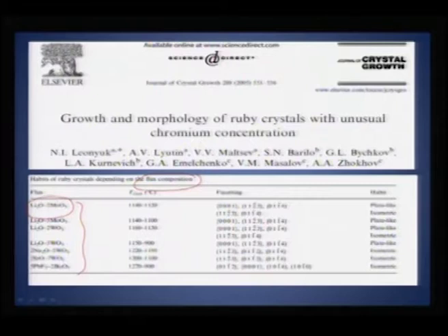If you take and put it in a furnace in a crucible, you can actually melt it between 1120 to 1140 degree C. Then this lithium oxide molybdenum oxide will form a melt, and in this melt if you drop some alumina with chromium oxide, then what you will get is ultimately a ruby crystal in a melt.